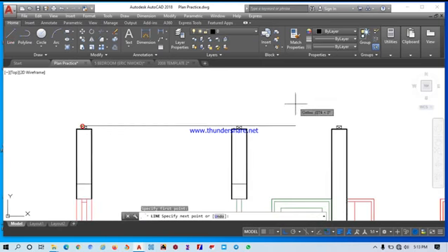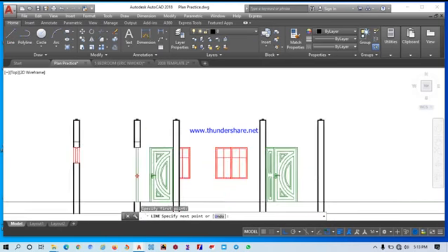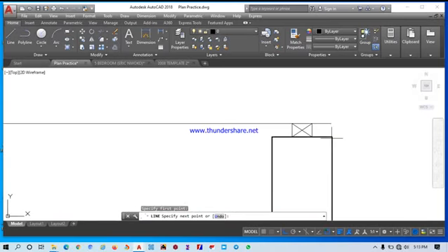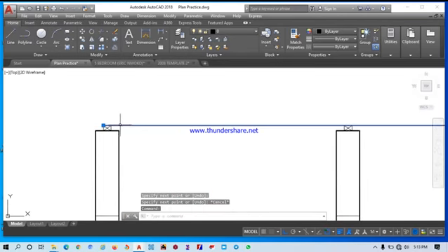our tie beam. A tie beam is one running across your building, whereby you can hang your ceiling. So let me use this as my reference for this edge. But mind you, the tie beam will be a little bit smaller. Some can leave it at that point, but most times it is a little bit more projected than your wall plate, just a little bit, and you can terminate it there.